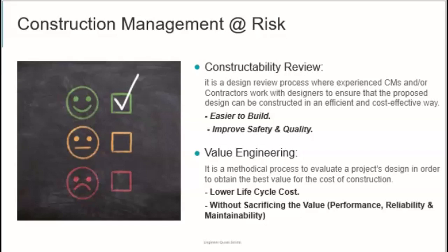So what is value engineering? VE is a methodological process to evaluate a project's design in order to obtain the best value for the cost of the construction. When we say cost, it doesn't mean we need to compromise the quality. So, lower life cycle cost without sacrificing the value, performance, reliability, and maintainability.